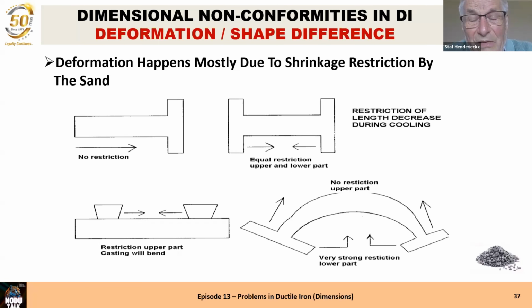Why did I tell you the strength of the sand is 3 and 3.5? Well, the casting solidifies very quickly while the strength of the sand is still there, and the sand can become stronger than the strength of the solidifying metal. In this case you can even have hot cracks in the corners, because the sand holds the flanges in place, and inside that connection shrinks, and you can get hot cracks.